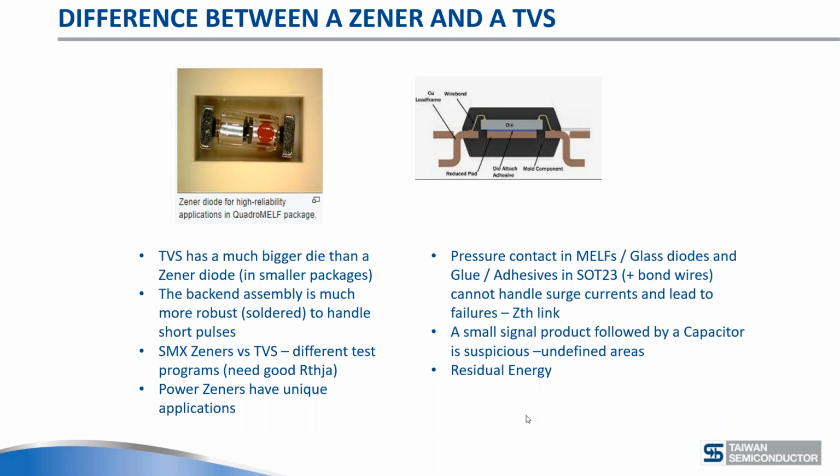And actually, when the package and the TVS react there, there might be a difference in voltage level or anything else later on in the circuit. That's what we call residual energy from the surge, and that can also damage a Zener diode. So these are two failure modes with Zener diodes that are well known and popular, or not popular, well known, I should say.